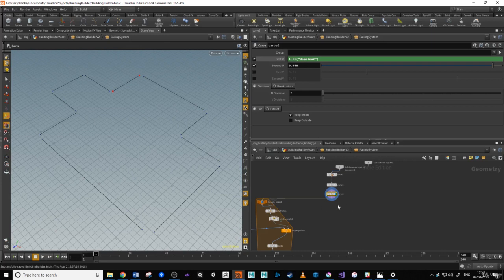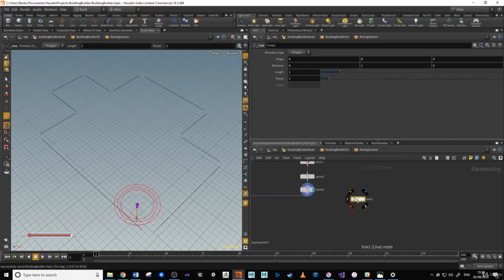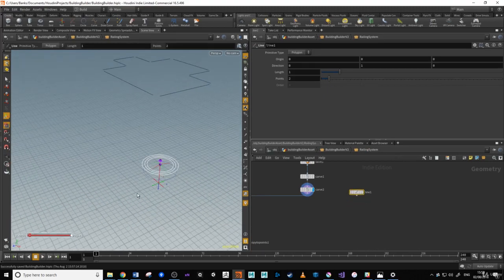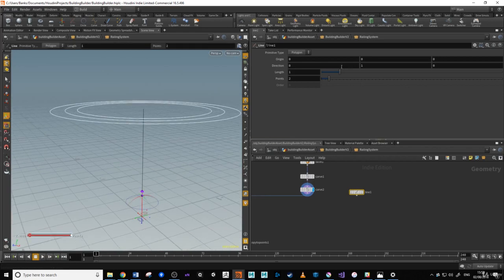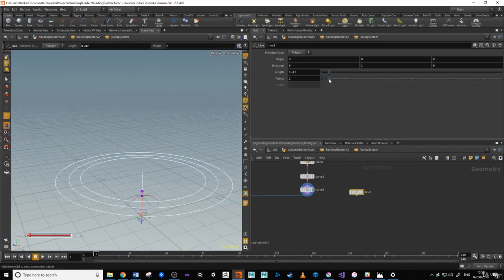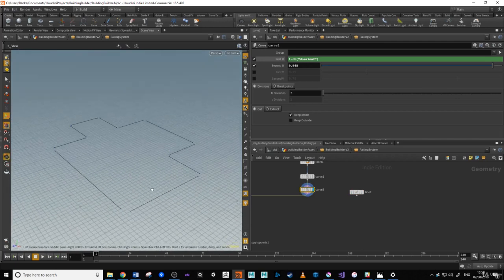on the railing system. So what we're going to do is we're going to put down a line SOP. Okay, and there it is all the way down there. So this is going to be our sort of the starting point for our uprights, and we'll have control over the height of them, and we're going to use our super sweep node so we get all our UVs and everything sorted out.